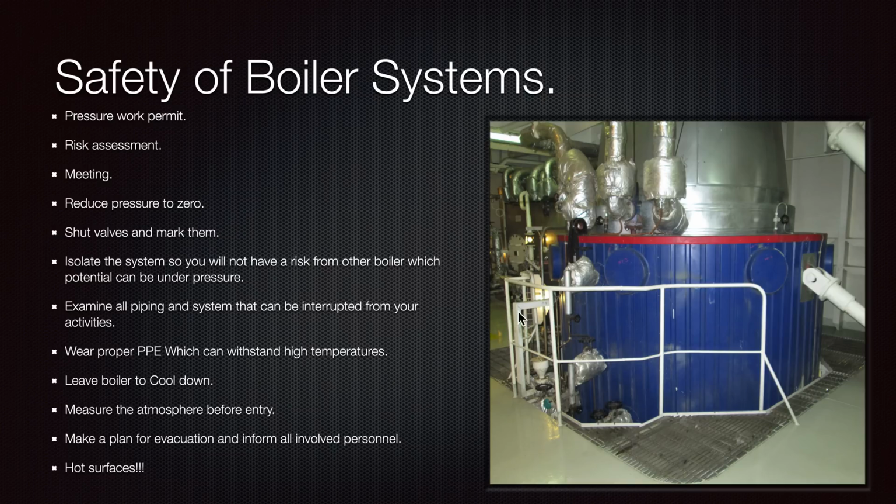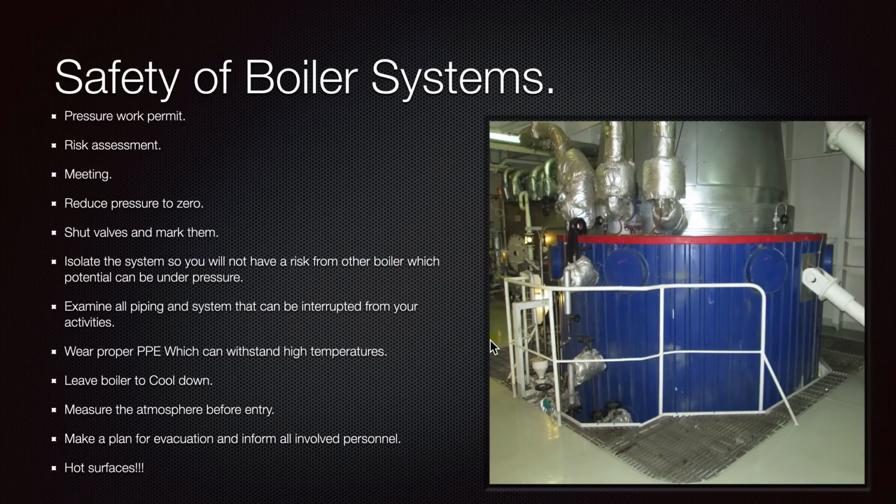In the boilers, an atmosphere can be created from the fuels, from the injection of the fuels, and if we have a burner which does not operate properly, the fuel will be dropped down, and this fuel, or the diesel, can create an additional hazard and an explosive atmosphere.